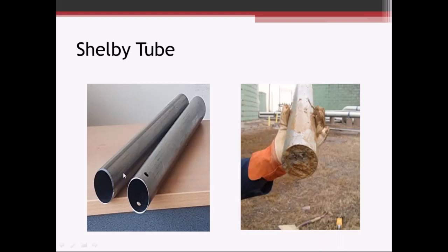And these are generally used for soft, cohesive soils. They're not used for gravel, sand, or very stiff, cohesive materials. And once the samples are collected, then the ends are typically waxed and sealed to retain moisture for transport to the laboratory.